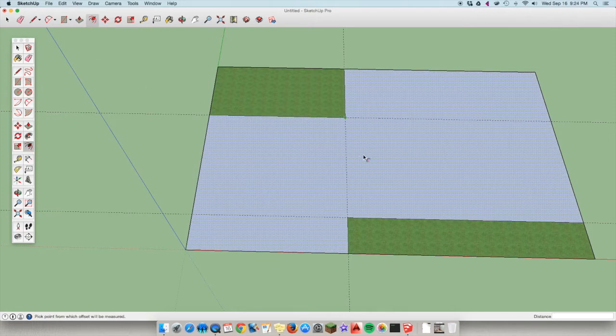I'm going to hover in the middle of our area here that the house is going to be. I'm going to click. I'm going to move around and you'll see this shape come up. Okay, we want the thickness of the walls around the outside of this building to be 8 inches. So I'm going to type in 8, enter. Okay, and then you get this shape.